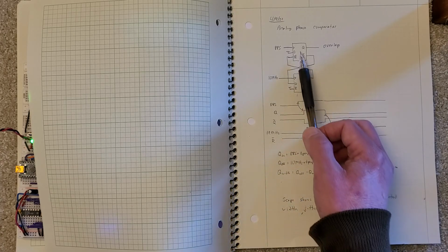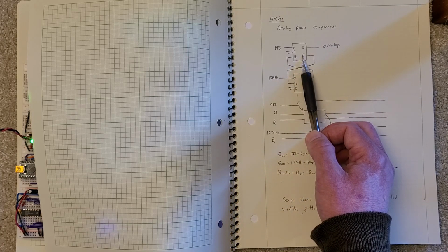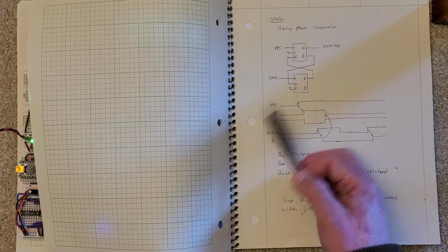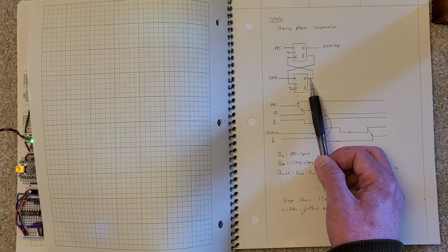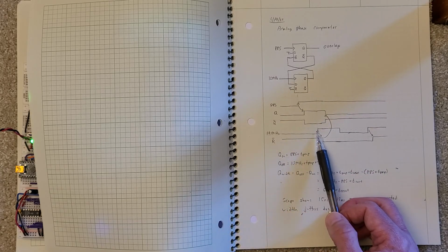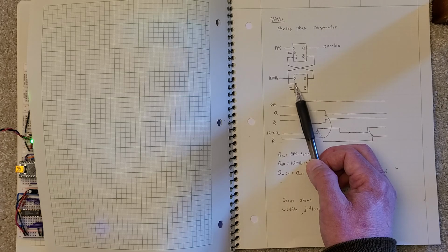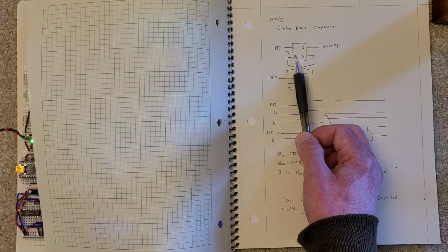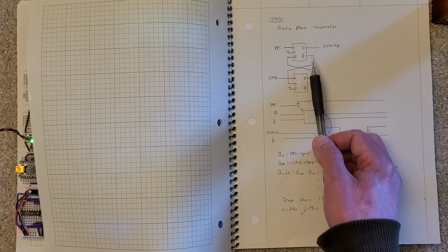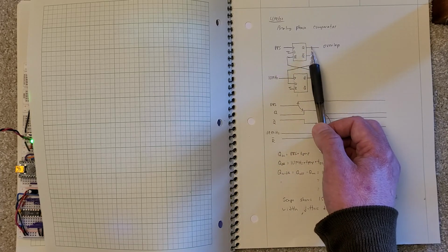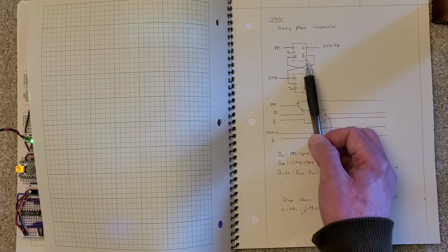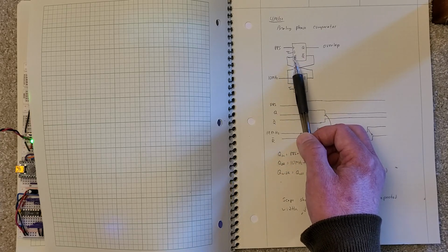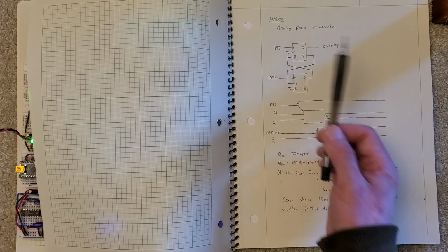It goes high, which means that the Q goes from high to low. Since the D is low, the previous one was high, so the Q is high. But when the 10 megahertz clock comes along, it makes the Q of this bottom flip-flop go low, which actually resets the top flip-flop. When this top flip-flop gets reset, then the Q again goes low, Q bar goes high, and then the reset is deactivated, waiting for the PPS to come along.